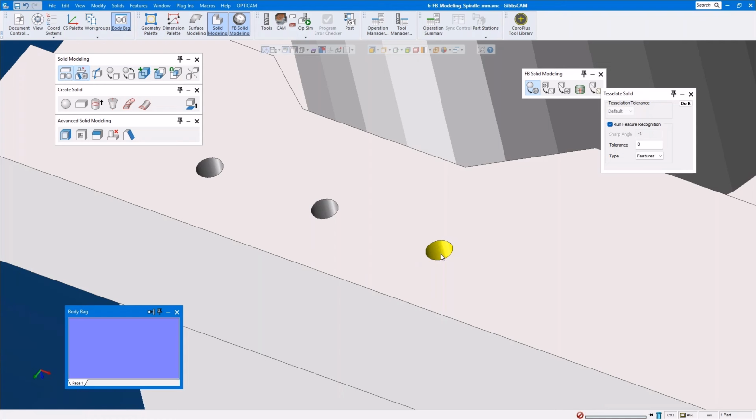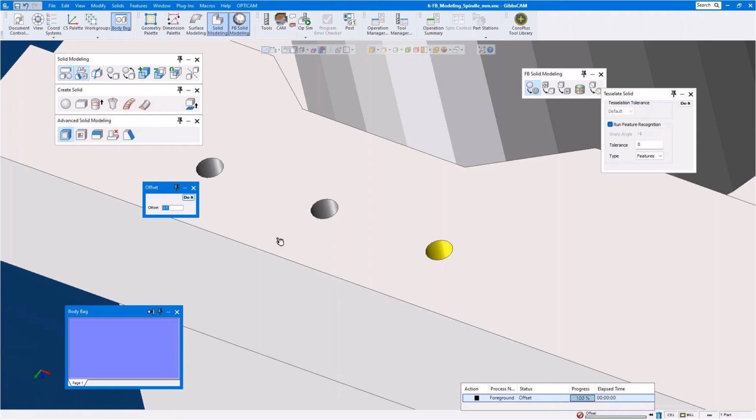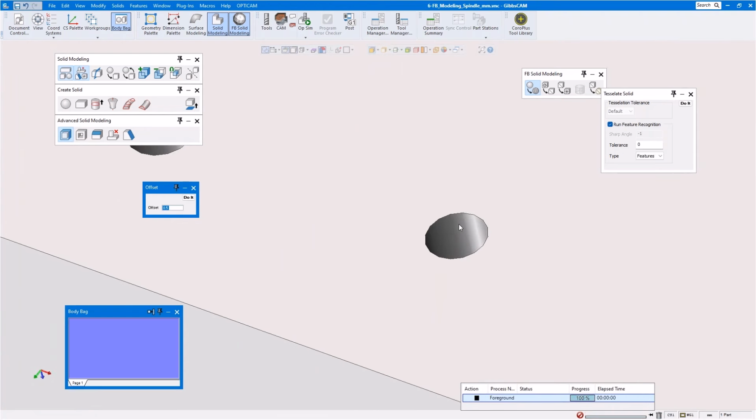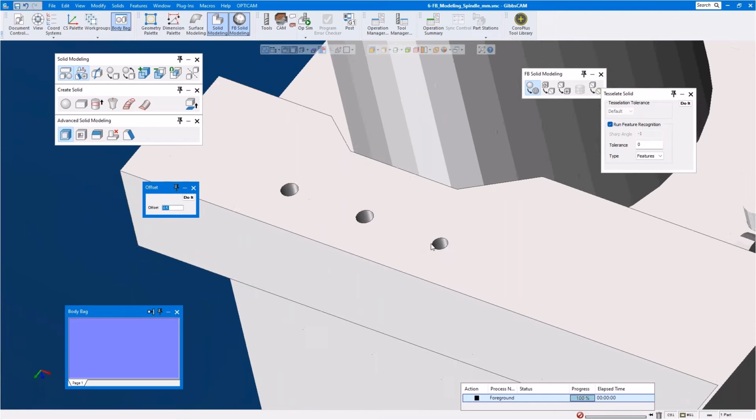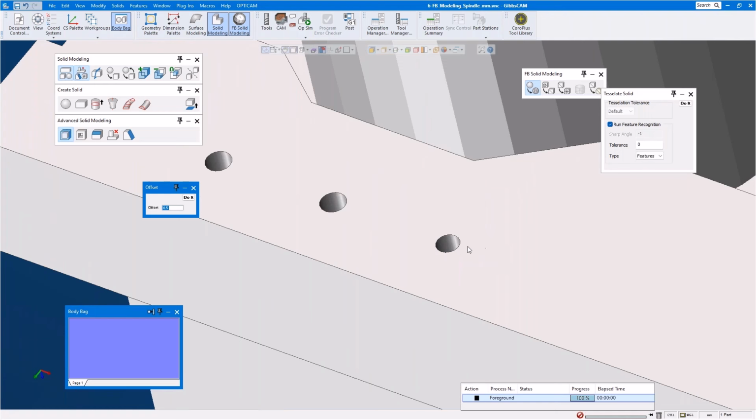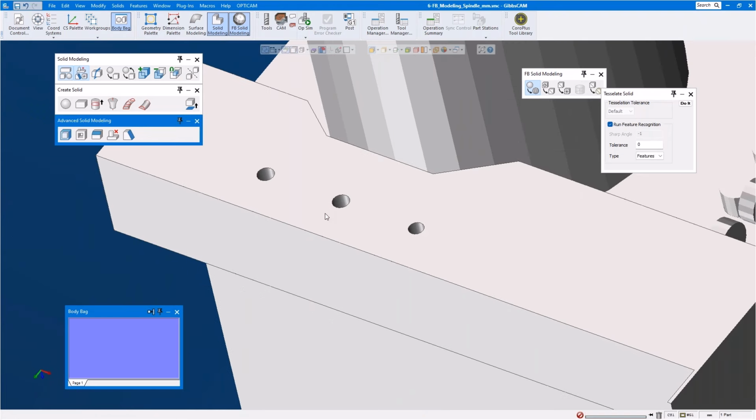It's just easier for us to work with. For instance, let's say I want to offset that face. I'll offset it 1/2 millimeter. It offset that 1/2 millimeter, all in one shot, selecting one face. Yes, in the background, there are multiple triangle faces there, but for our working with it, we can use it as one face, which makes it all easier for us.